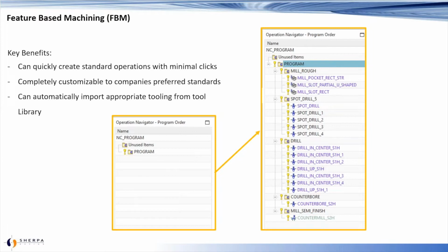Right now, it's a little bit tricky. You have to go through the machine knowledge editor. Typically, that's a job for an NX admin, or you outsource it through a contractor. They are improving that to where you won't need the machine knowledge editor, but it's not quite there yet. You'll see it soon, probably in the next couple releases.